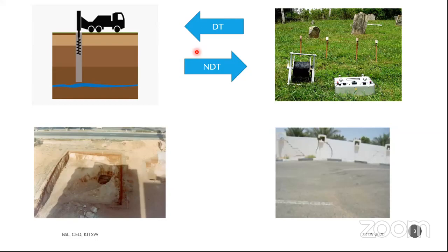So one of the case studies I encountered is in Bangalore, where I found very hard soil strata. At the depth of 1 meter, I found very hard soil, like stiff clay. The first problem I encountered is that the electrodes cannot be driven so easily. Like, to our common sense, I cannot drive my electrode in a rock. This is the first encounter I faced on the site.